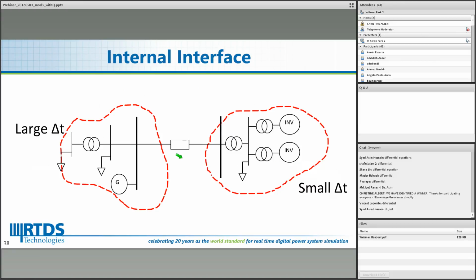In this case, I believe many people here are familiar with all those existing models in the RTDS small time step library. Sometimes we use the interface transformer and sometimes we use the interface transmission lines, but the underlying algorithm behind either the interface transformer or interface transmission line is the transmission line, and the length of a transmission line is 1.59 large time step.